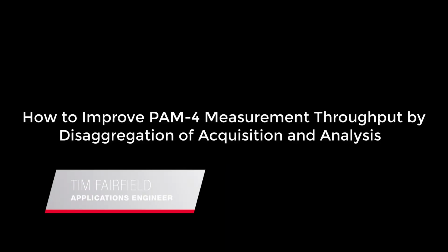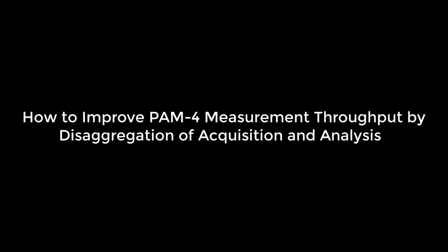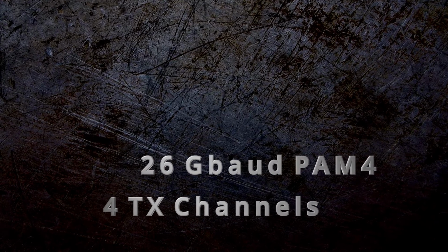This video demonstrates how measurement throughput can be increased by the disaggregation of test signal acquisition and signal analysis by running several of these processes in parallel. As a practical example, we measured and analyzed a 200G transceiver consisting of 26 gigabaud PAM4 signals from 4 transmitter channels.